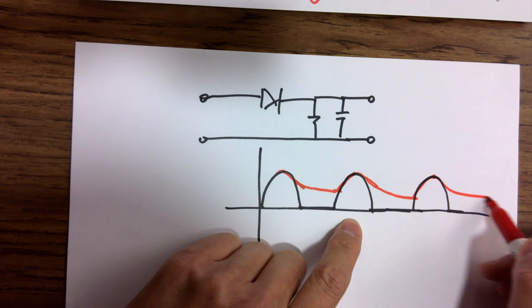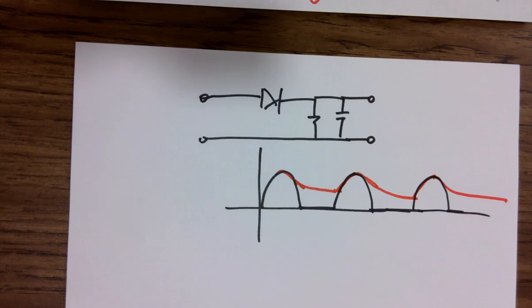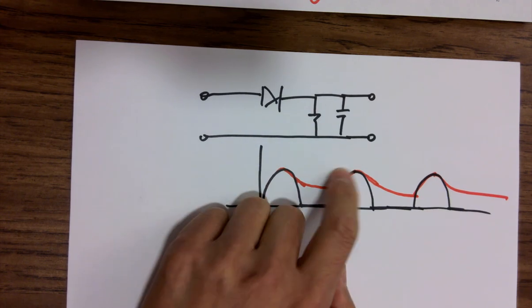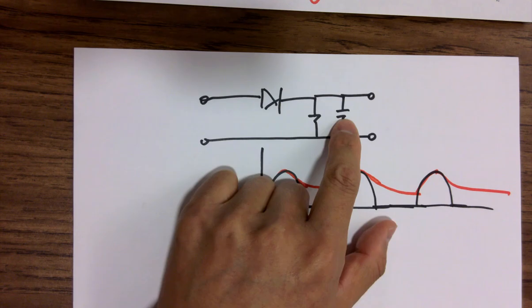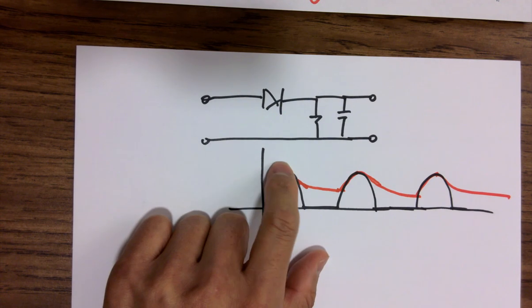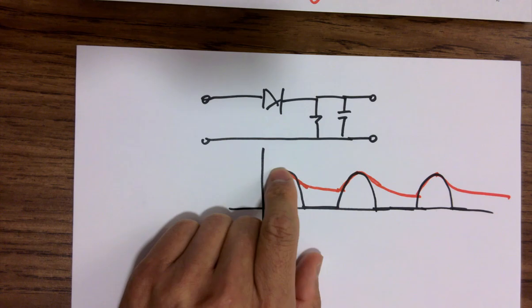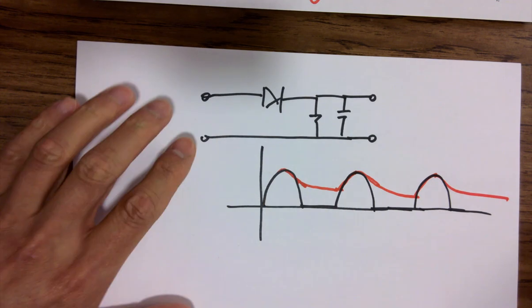And that reduces the AC component, right? It looks more like DC, but you have a lot of ripples, right? Depending on the resistor and capacitor values you are choosing, you can have a big capacitor to maintain the charges more steady, more stable, and then you have less ripples, less changes over here. But this is a half wave. This is called a half wave.